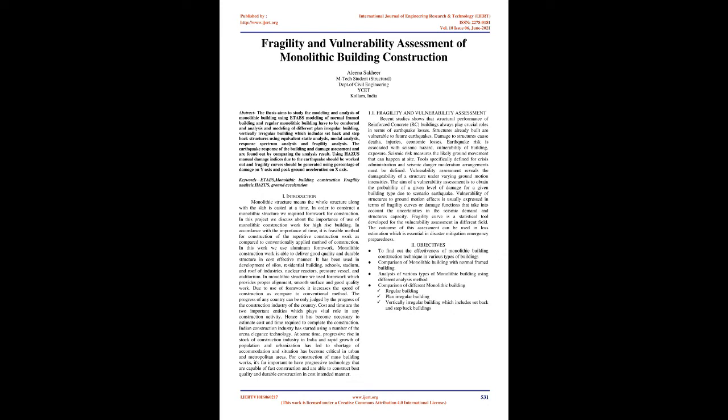Vulnerability of structures to ground motion effects is usually expressed in terms of fragility curves or damage functions that take into account the uncertainties in the seismic demand and structure's capacity. Fragility curve is a statistical tool developed for vulnerability assessment in different fields. The outcome of this assessment can be used in loss estimation, which is essential in disaster mitigation and emergency preparedness.